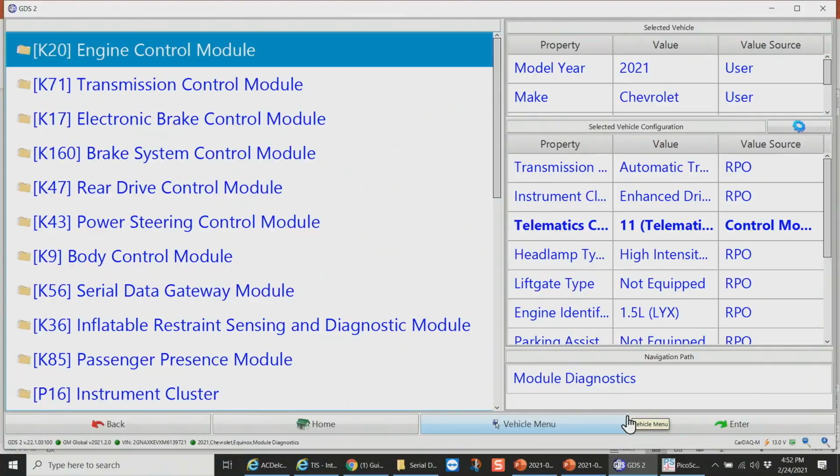So like the old school bus covers that covered the grille for better heater performance, but then when it got warm, you had to take those covers off. This is an electronic version of that, working off a LIN bus command from the ECM. So the ECM is here on my scan tool. Your scan tool may be able to also operate. Chevrolet Equinox 1.5 is what we're working on right here, the car in your bay. We're going to go into the ECM.